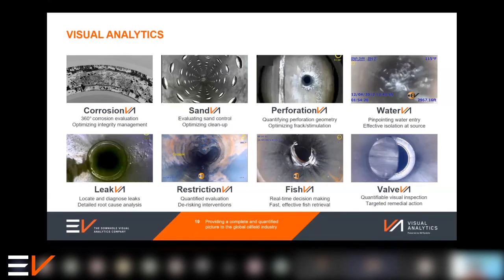We can design things, customize them for a particular well. And going back to Richard, yeah, for cleaning up whilst we're in hole, there's several solutions for that, such as pump down through the kill line with a clear fluid. There's the bullheading, circulating through a coiled tubing. Also, if we are in a workover, we can run through drill pipe, and you can circulate through the drill pipe, which is just above the depth of interest, to give you a really clear environment where you may have well control issues.